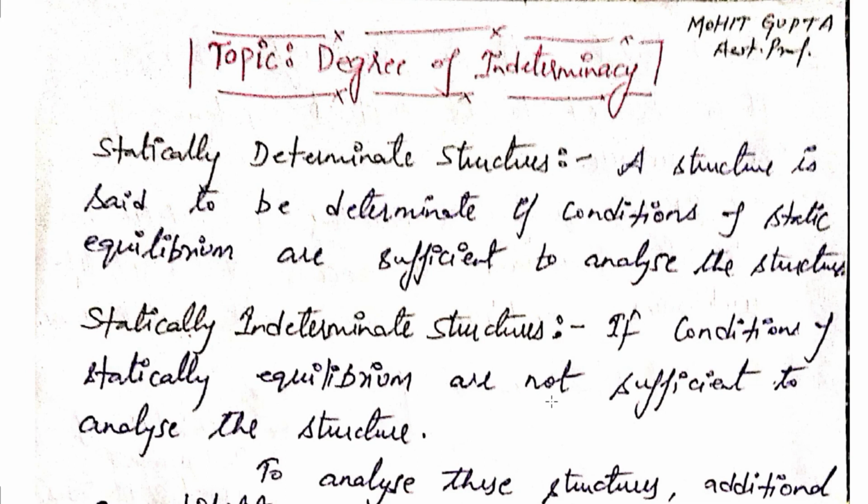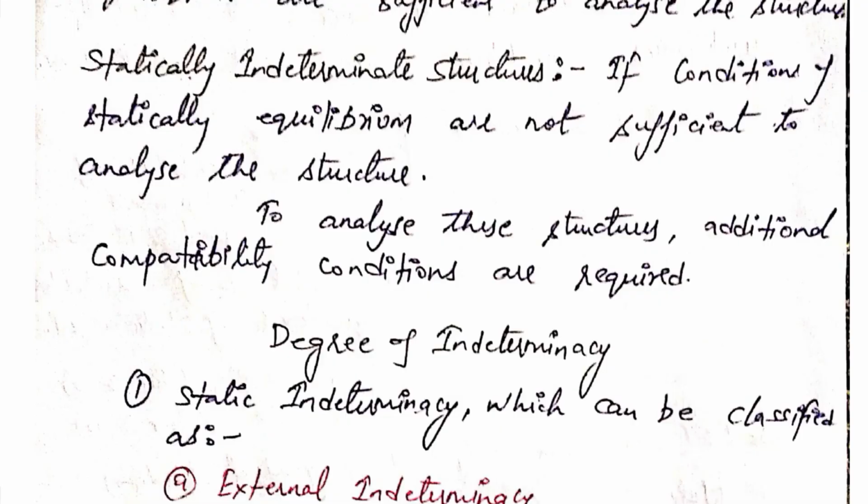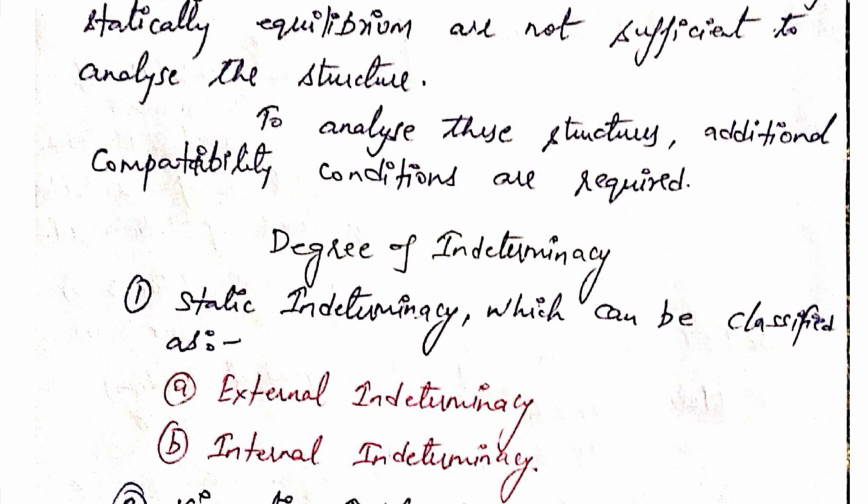In indeterminate structures, bending moment and shear force do not depend upon the properties of materials and also not upon the cross-sectional area. Stresses are induced due to temperature variation, and also due to lack of fit and support settlement.